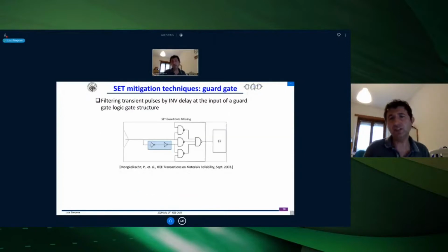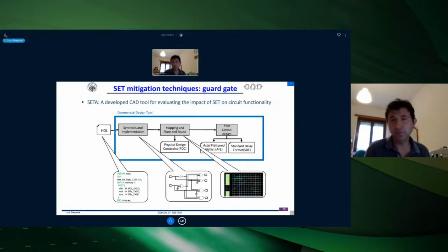Well, all of this can be applied to mitigate SEU in the configuration memory. Transient effects can include, for example, guard gate filtering. The guard gate filtering is implemented in some rad-hard FPGA, and instead in COTS FPGA, you should implement it manually, basically. So you need to implement it by means of VHDL or using place and route techniques in order to insert macros for the filtering. So it's not implemented automatically with the technology. Or eventually use some tools.